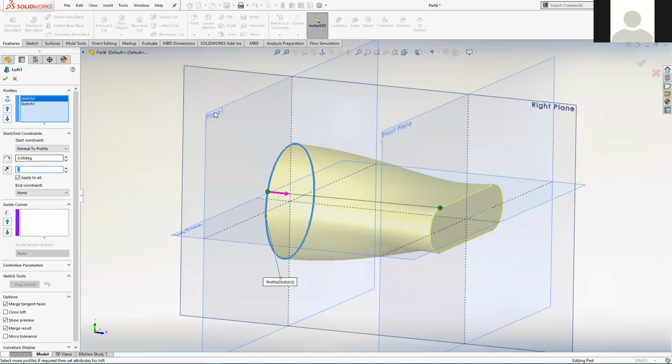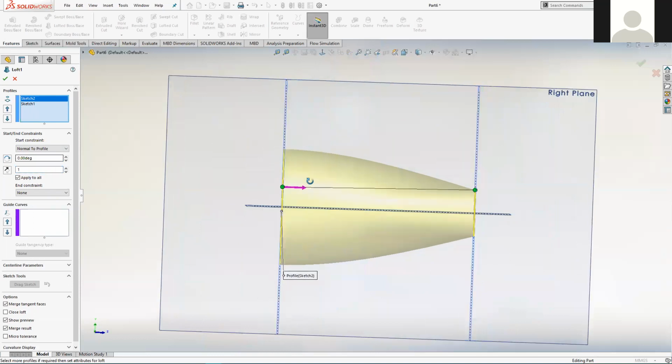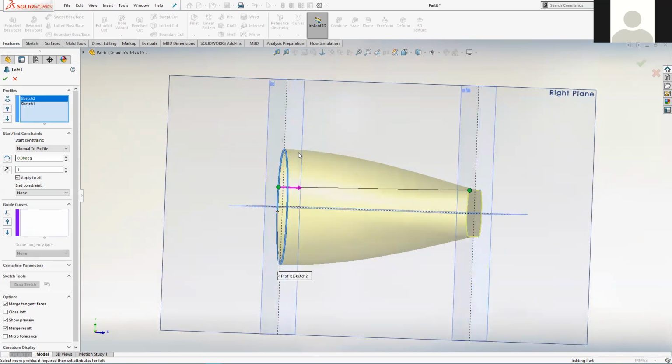The first sketch is sat on plane 1 there, so that when we put normal to profile, the influence of that sketch extends somewhat into the actual loft shape itself. So you can see its influence is tapering away the deeper into the loft that we go, until eventually, down towards this end, we resume that almost straight line again. But certainly initially, this shape persists into the actual loft shape itself.